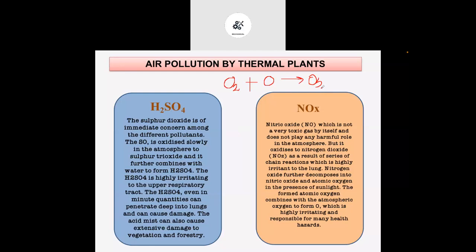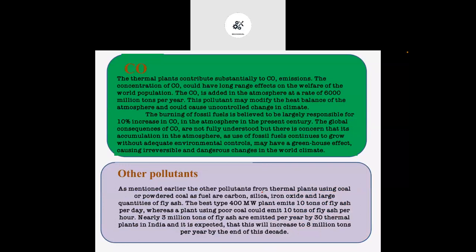Okay, this ozone is useful in reflecting the UV rays from the sunlight or the sun radiation, but it is toxic and dangerous to the human body. So whenever atomic oxygen breaks out from the nitrous oxide, it will react with normal oxygen and create ozone, which is again dangerous to the human body. Another pollutant coming out from the combustion is carbon monoxide.